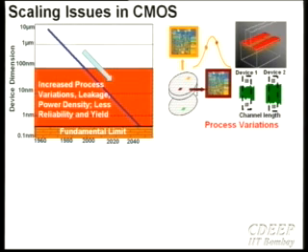Earlier, when it comes to, for example, analog design, people were worried about those things, not that they're not worried about them today, but what is really important to notice is that some of the things that analog designers were concerned about in the earlier days, these days digital designers have to consider too. So considering which process corner you're in, then taking some corrective actions, self-tuning, self-correction, they turn out to be actually important in today's CMOS circuits.